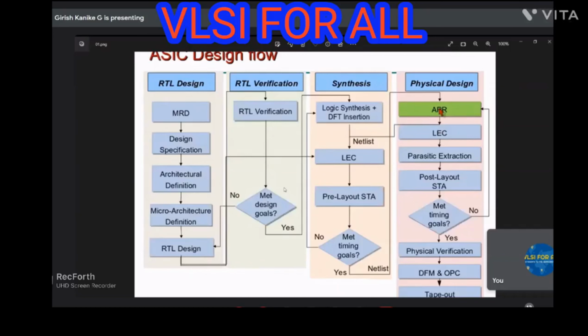Mapping means which pin needs to be connected to where. Like if there is an AND gate, the input of the AND gate is drawn from some other gate. That will be written in a code manner and converted into a diagram, in a gate manner. After that, there will be an optimization stage where whatever mapping is there will be optimized and logically corrected, so that it is reduced. There are no lengthier wires to be connected, and no illogical connections present. That happens in the logic synthesis.